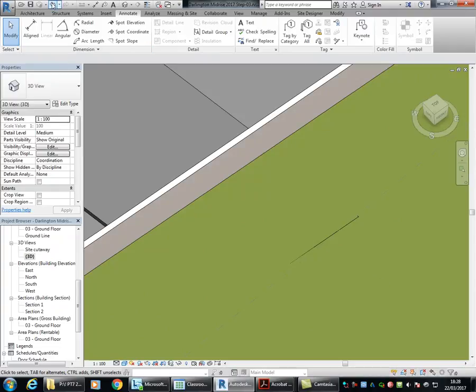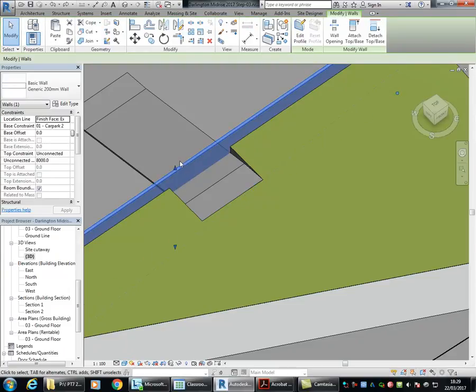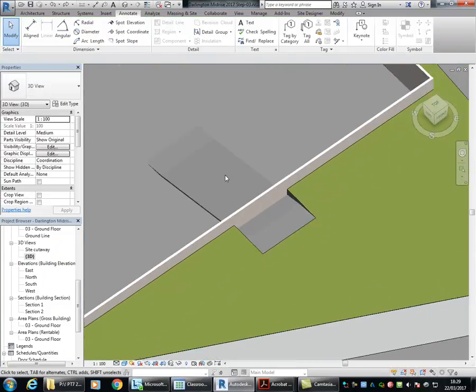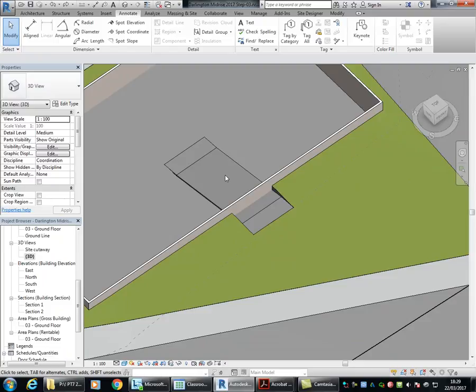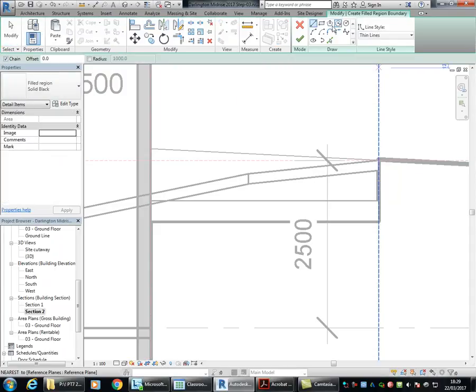But just by putting the pad in, we can see the ramp in the 3D views, and the 3D views are an important thing for this project, because you'll need to obviously create a lot of hopefully really good quality renderings towards the end, and so that's an important thing you need to be able to see, and then of course you're going to see the doorway in your wall once you do that, and so also when you do the next ramp you may have to do the same thing, but again in section, I'm sure you all know, you can make things like regions to cover up all those messy things you might be left with, so that's probably the option I'd be using.